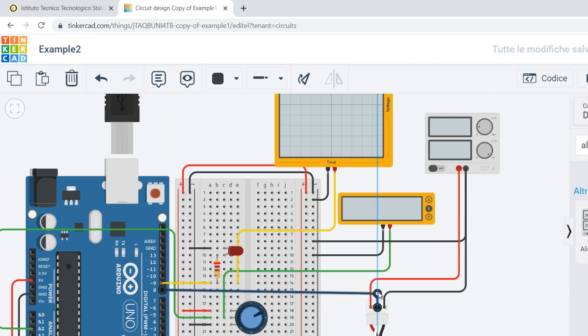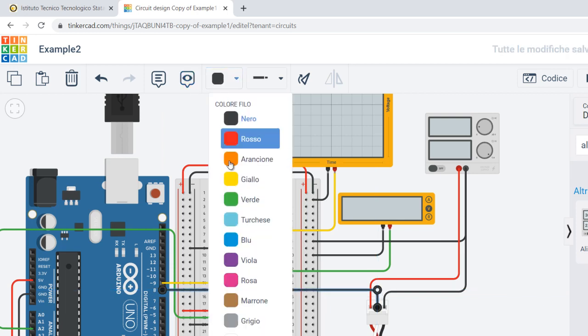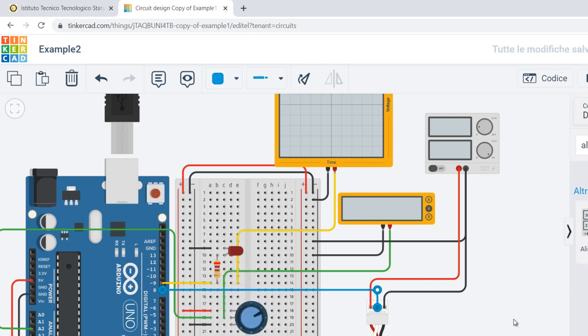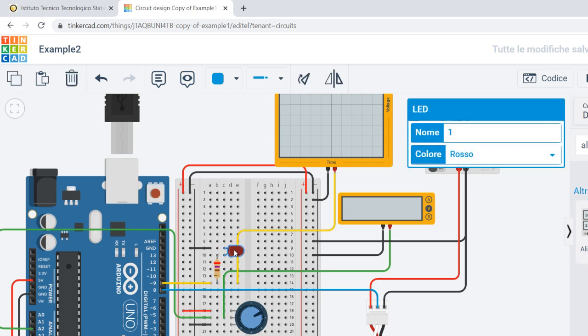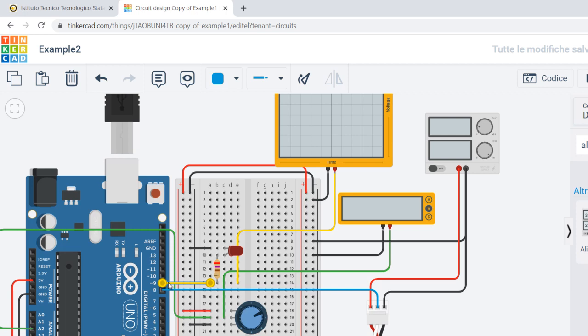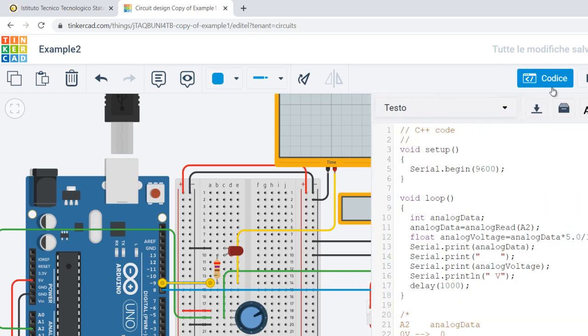And we select the color, for instance, blue. Okay, so we have all the connections we need. First of all, we want to regulate the duty cycle of the PWM form on pin 9 based on the voltage read. So what should we do? We can say that